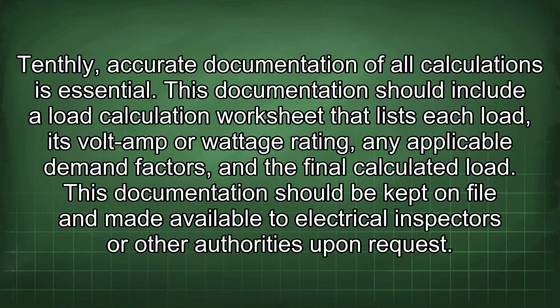Tenthly, accurate documentation of all calculations is essential. This documentation should include a load calculation worksheet that lists each load, its voltamp or wattage rating, any applicable demand factors, and the final calculated load. This documentation should be kept on file and made available to electrical inspectors or other authorities upon request.